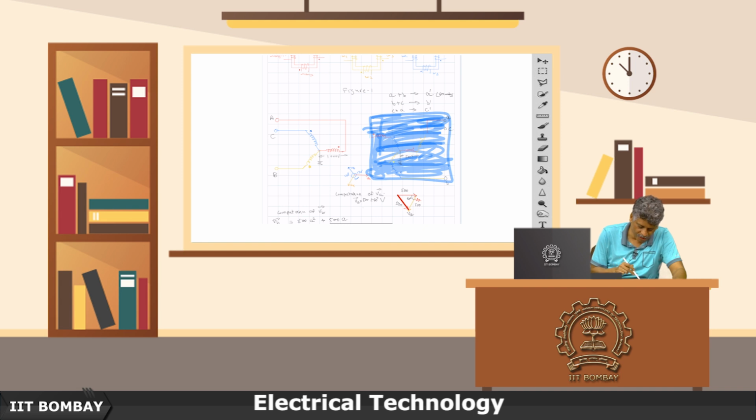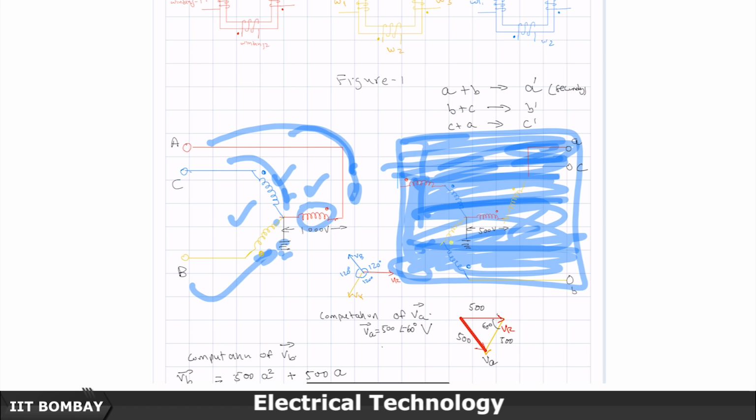So, for each phase you connect, say, these three primary cores of the transformers, they effectively become like inductors, reactors, and you ground it. Then what will happen? Because of the leakage impedance, let us say 1%, 2%, then 10%, a huge amount of current will flow here to the ground. Though it will sum to 0 because of being balanced, each one of them will be carrying a large amount of current. This situation is unacceptable, because then the whole current profile in the system, in the wires, has gone haywire because of these ground currents.